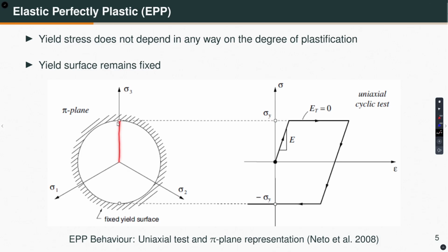what will I do? I will move along this path. That is what I am showing: the stress versus strain response. We are moving along this path. I have already shown this using OpenSees, but there I drew the yield surface in the principal stress space, sigma 1, sigma 2, and now here I am showing it on the deviatoric stress space. Remember, some authors call the deviatoric plane that is passing through the origin a pi plane, but some authors call all the deviatoric planes pi planes. That is what is shown here, the pi plane, which is basically the projection of the von Mises cylinder when you are looking along the hydrostatic axis.